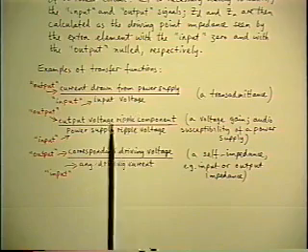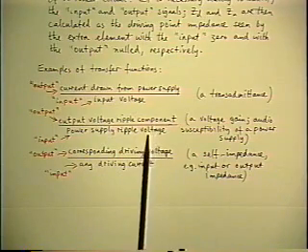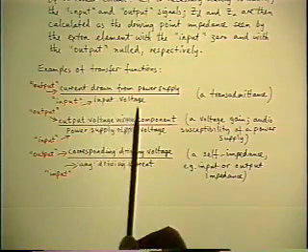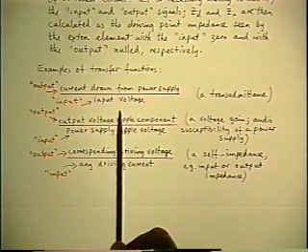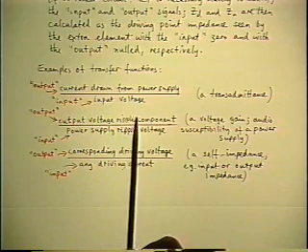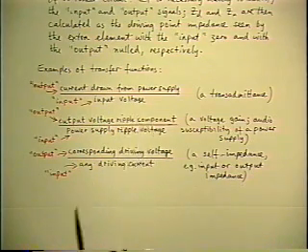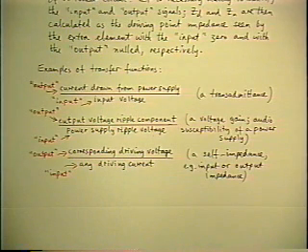For example, when you're designing, say, an audio amplifier, the signal input voltage, of course, is the principal independent input signal. And normally you're interested in calculating the gain, which is the signal that comes out of the amplifier. That's your principal specification. But the input signal does something else as well. It also determines the amount of AC current which is drawn out of the power supply for your amplifier.